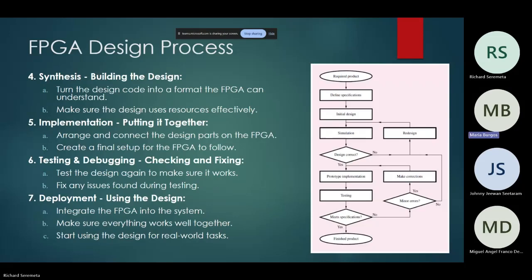This means each component of the design, such as the logic gates, the AND or NOT gates, flip-flops and other digital elements, is represented by its corresponding gate-level description. These descriptions map the logical operations to physical hardware resources within the FPGA and instruct the FPGA on how to create the physical circuits needed to execute the design. Also, during this stage, it is important to check and make sure the project uses the computer's resources efficiently.